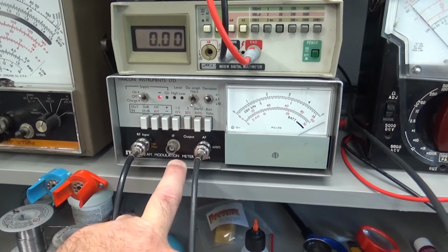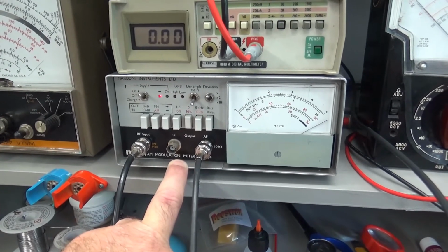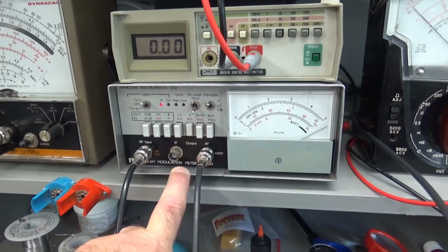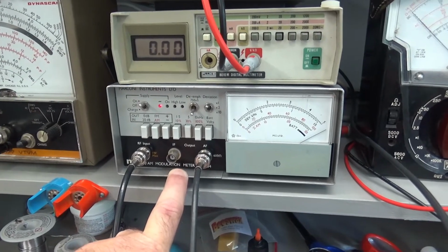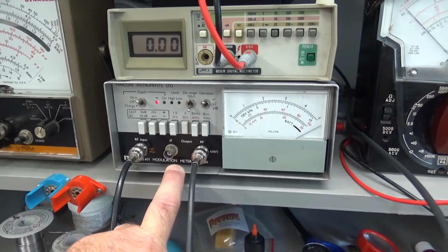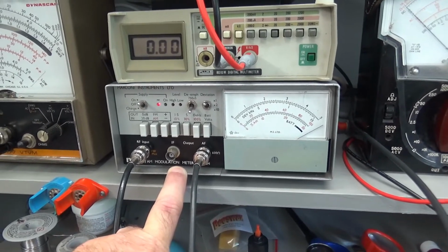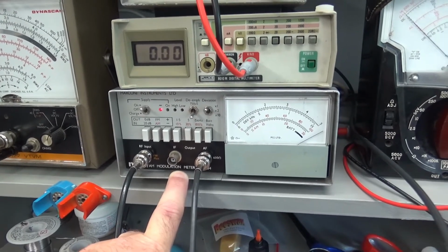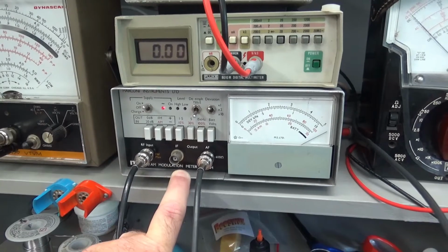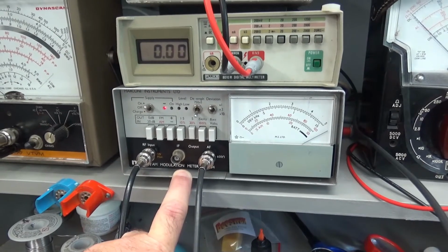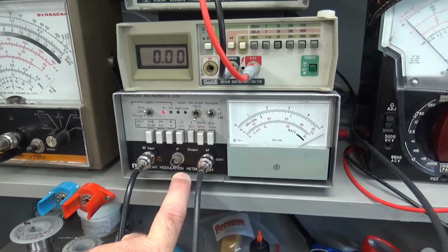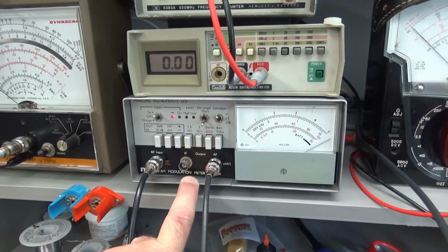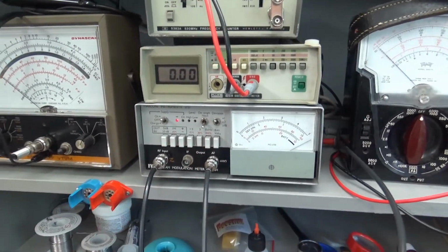It had a little bitty coil, a little ring mixer coil, and that thing had little rubber insulation on each leg. It had 4 connections, I believe, but that insulation, that rubber, had decomposed, and it ate into the copper of the little transformer, and it wasn't mixing properly, and so it made the sensitivity really bad. Anyway, I was able to repair the coil, and this thing works like a champ now.